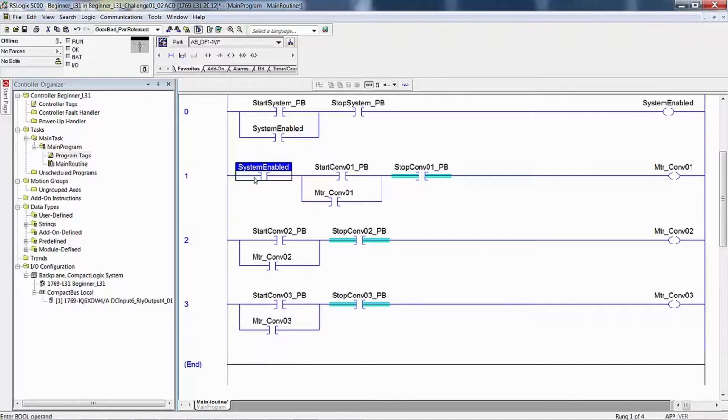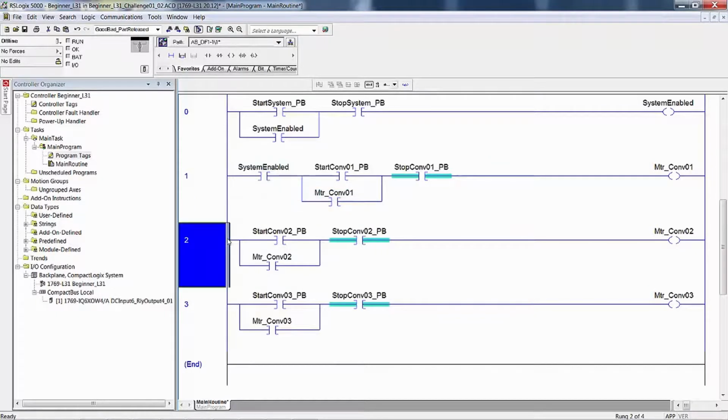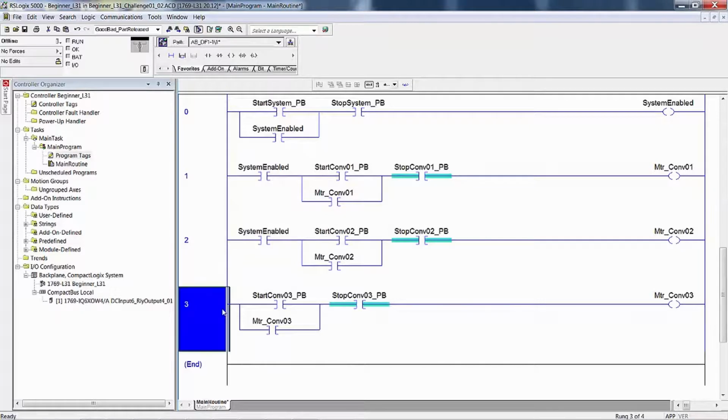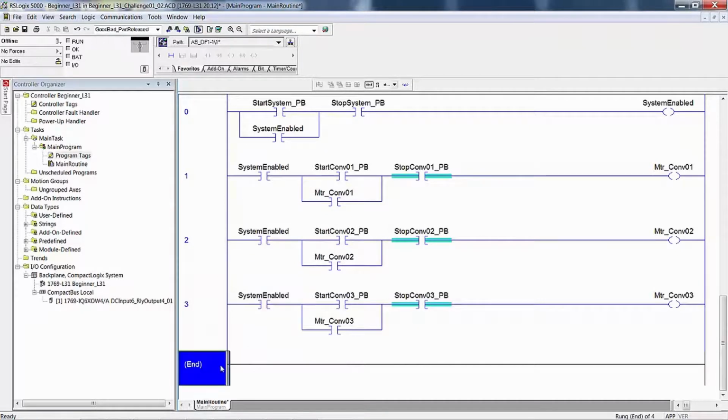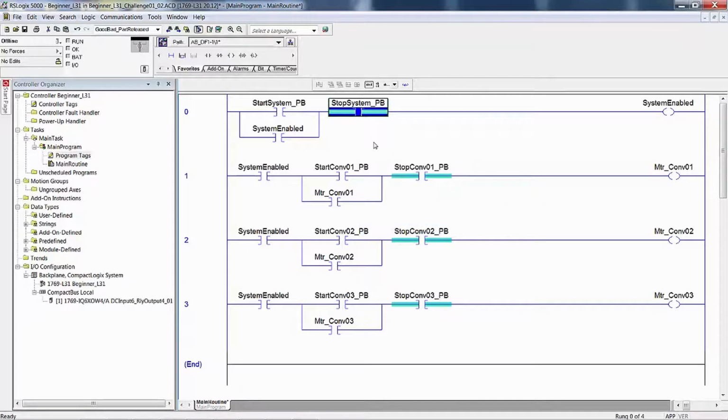Now there's many ways you can do this. You can repeat what I just did 2 more times, or you can right click, copy, click there to bring the focus there, Control V, select, Control V. Okay, now if the operator, and by the way, this would be turned on, so we'll toggle that. Now we're not online right now, but we do have an offline database. I just toggled the bit on in the offline database so this would look right. So right now all the stop buttons show that they're on.